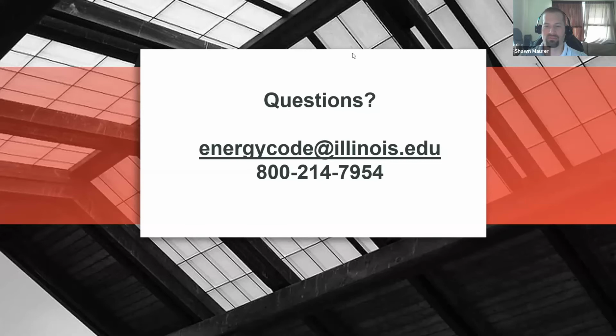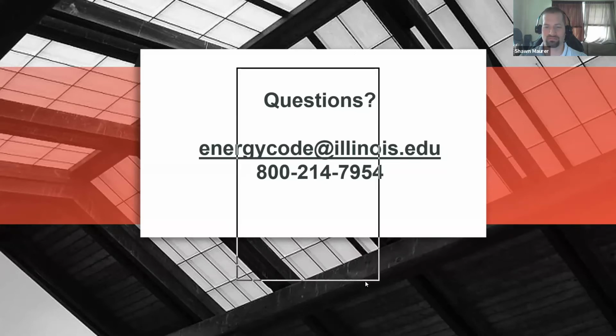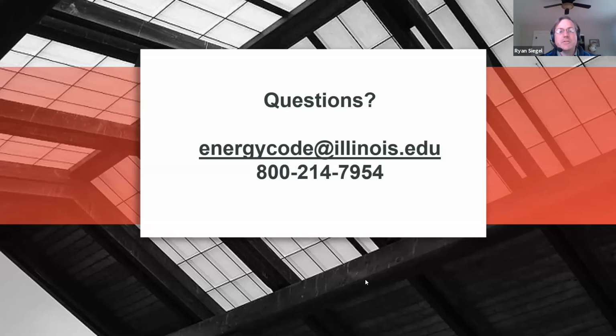Okay, looks like we've got most of our poll responses in, so we'll go ahead and share those results. As far as lighting controls requiring inspection, they include the following: occupant sensors, yes; daylight responsive controls, yes; light switches, no; time switches, yes; and decorative lighting shutoff. So I realize light switches is a little bit of a weird one because most occupant sensors are light switches too.